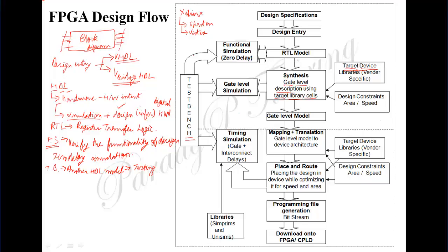Now, there may be different possibilities over here. For example, suppose we have written the code for simulation. Sometimes the constructs which we choose for simulation of hardware may not be suitable for synthesis. Therefore, sometimes we may have to choose different constructs which are synthesizable, and at the same time, the simulation results are also good. There is something called a simulation and synthesis mismatch, which we will have to avoid at this point of time. Sometimes it may happen that while simulating, we disregard the actual inference of the hardware from a particular HDL code.